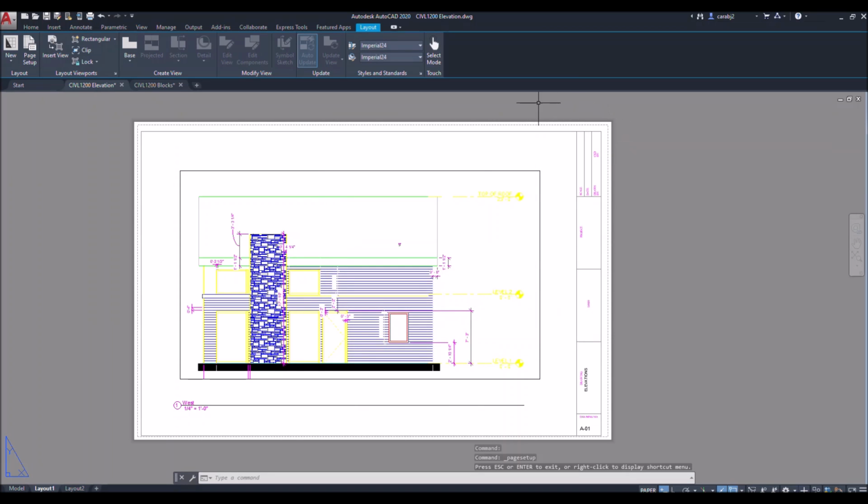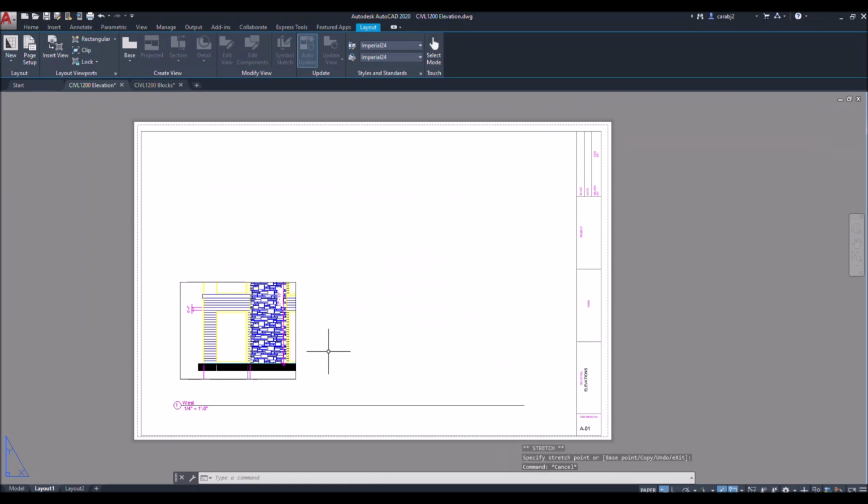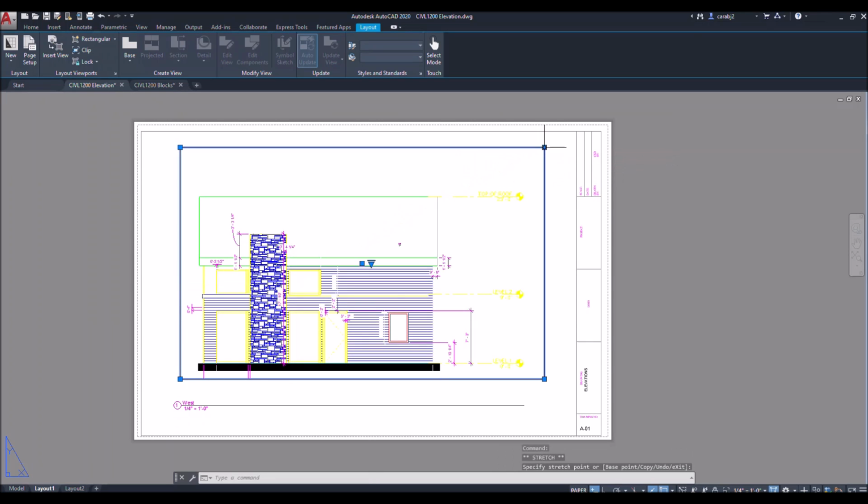And it should change your paper space to 11 by 17, but your viewport itself might look like this. Don't worry, that's not wrong, it's not printing wrong or anything like that. Remember, you can just select this rectangle, this viewport window, and you can see that there are two dots over here, the endpoints all around, and what you can do is just adjust this layout.